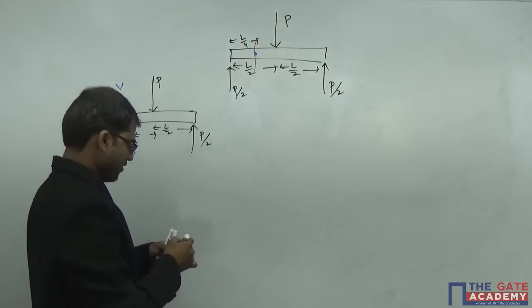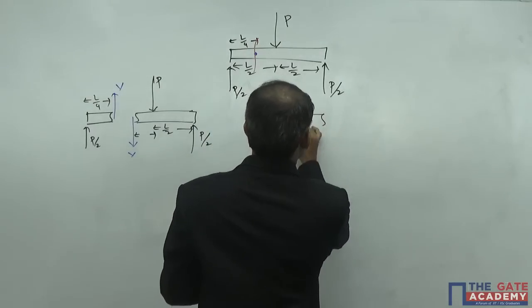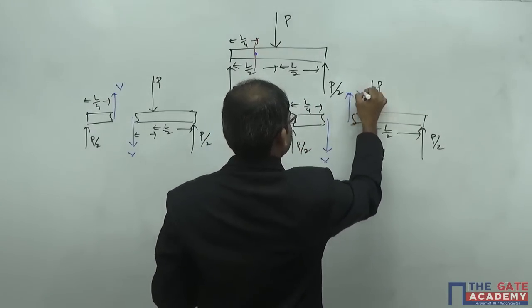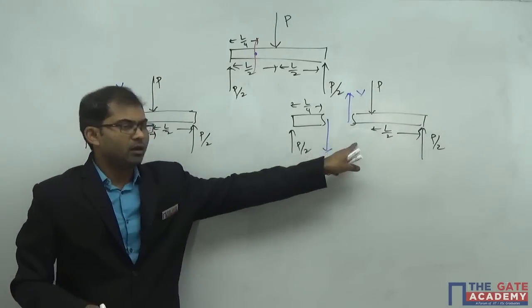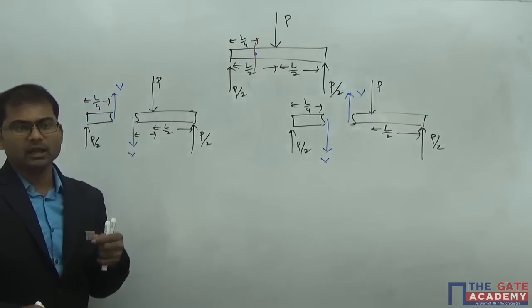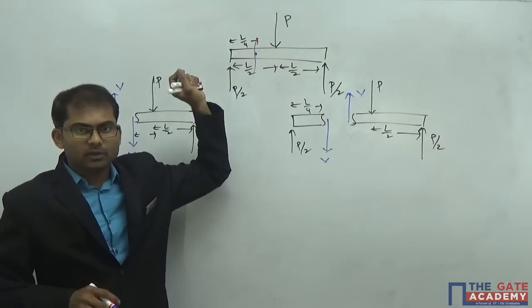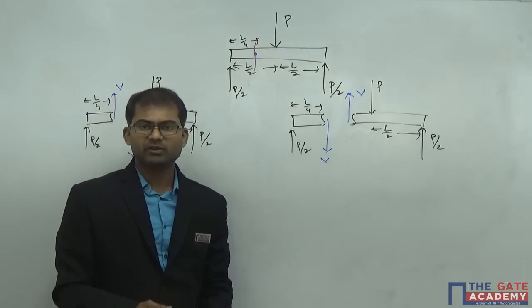In the same way I can go by the reverse condition also. So here we'll be having shear force V. So the arrangement is different. Either you can go this way or this way. Anyways, you'll be getting net load equal to 0 at this particular point because no force is being acted here. Now, to evaluate the value of V, we again apply equilibrium equations.